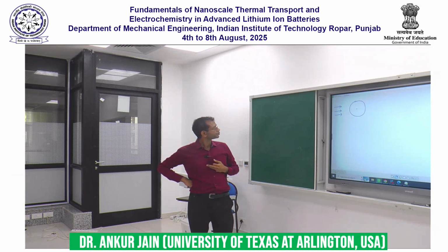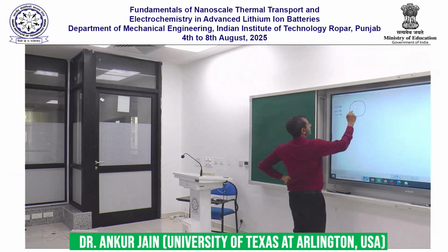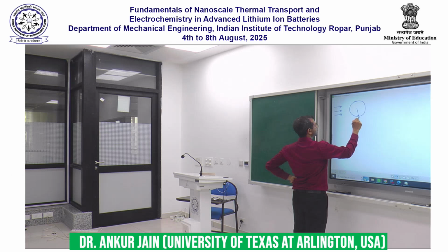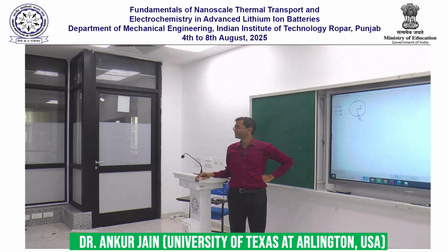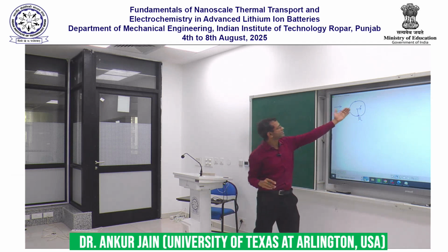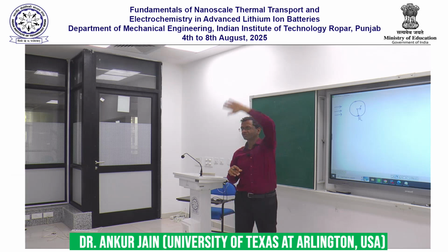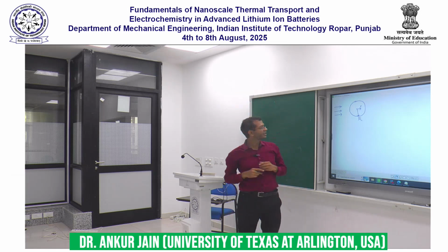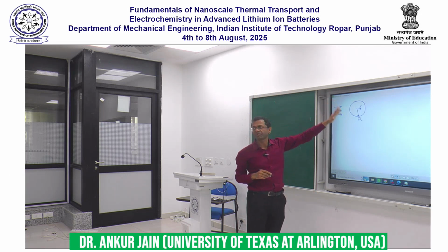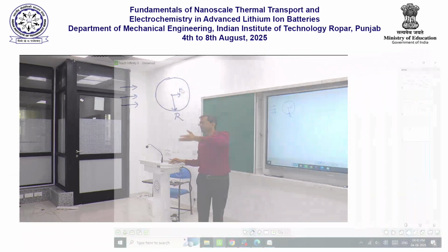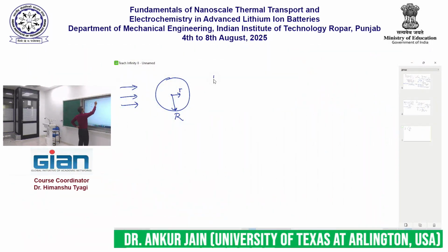Okay? So suppose the radius of the cell is capital R. I'm going to work in the radial coordinate system here. Let's assume that the cell is infinitely long, so that it's a one-dimensional problem. The cell is also axisymmetric from 0 to 360 degrees, right? So under a bunch of those assumptions, I'm jumping forward a little. We'll cover this in the lectures tomorrow, but the governing equation